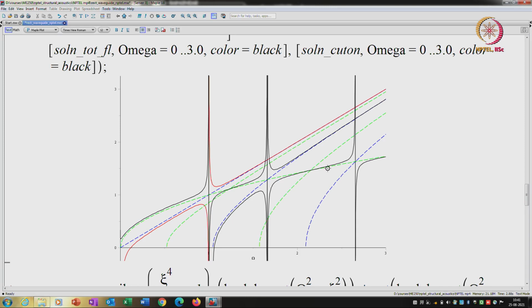Now the plane wave correction is below the original, below coincidence, this is the coincidence omega equal to 1, and the correction is above coincidence. So the plate is looking like a stiffness here and like inertia here. As inertia becomes more and more, we approach the plane wave original.